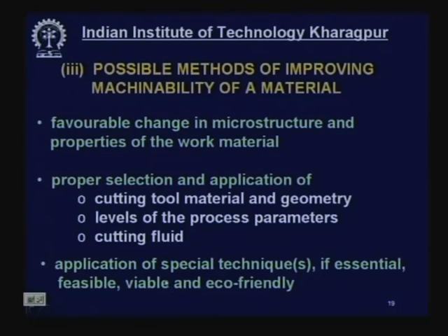So, if we can select and employ these parameters, techniques and environments properly, we can improve machinability substantially through reduction of cutting force and its consequences, cutting temperature, improving surface finish, reducing tool wear rate, that means improving tool life, and improving surface property. Not only surface finish, it is surface integrity as a whole, and we can also get a very favorable chip. So, this has to be done.